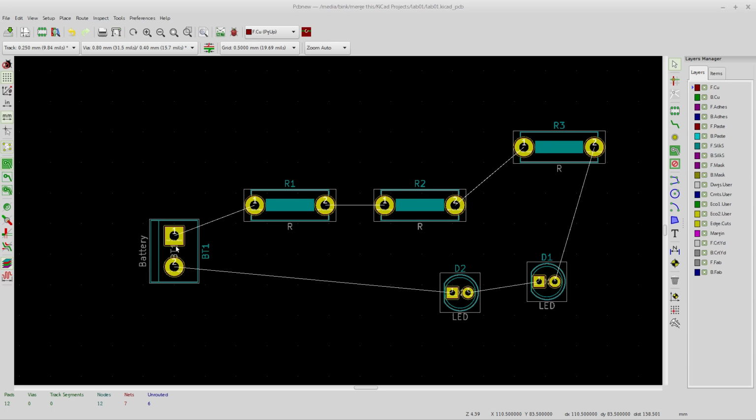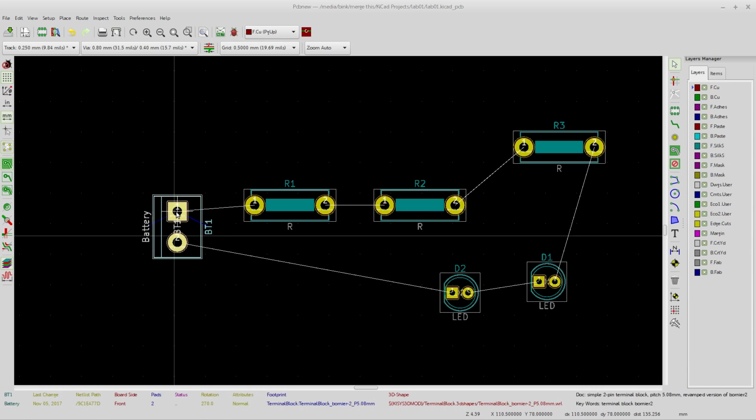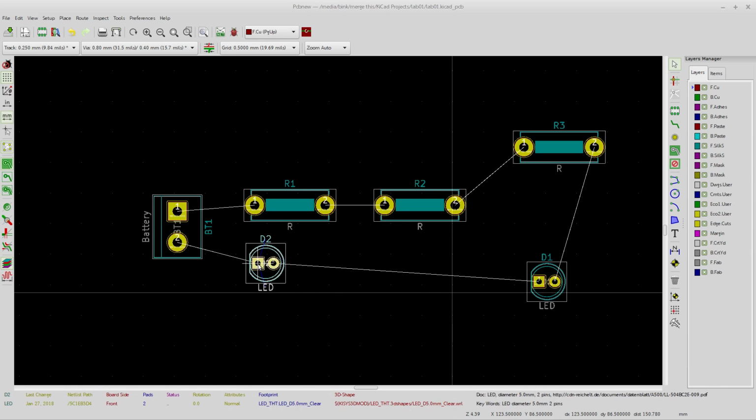With these terminal blocks, or pins, sometimes I make ones that are just plain pins, so I could use them for holes or test points. I maybe don't want a bunch that have positive and negative, others that are negative positive, and some that are blank. So if I just leave them blank, a lot of times for me it's fairly obvious which way is going to be which.